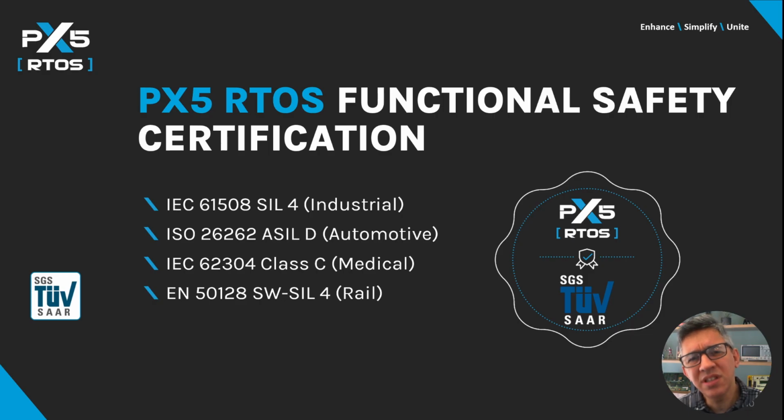Now, looking specifically at the runtime side, PX5 RTOS can be used in applications requiring the highest IEC 61508 certification classes, which means devices requiring SIL 4, ASIL D, Class C, and SIL 4 can instantly leverage PX5 RTOS and middleware in their designs.